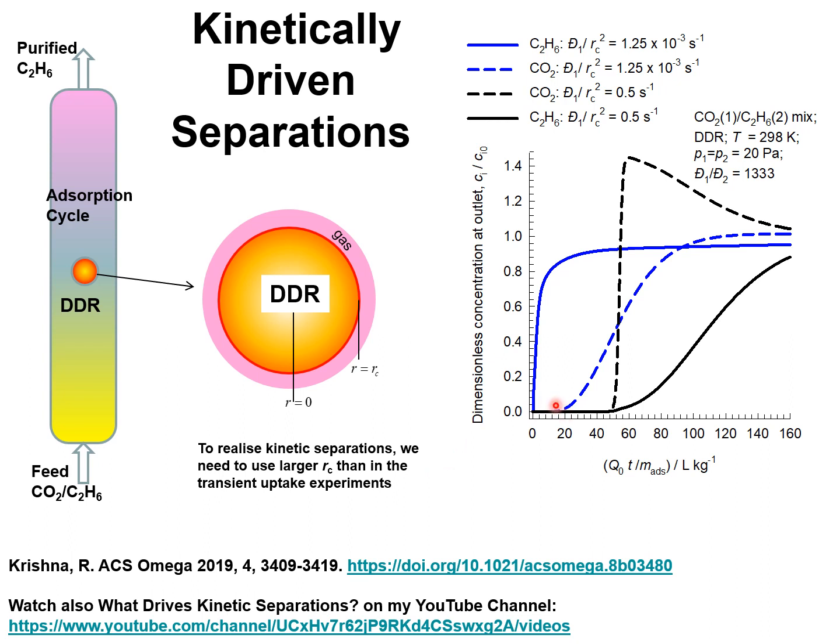The two scenarios are shown here. The blue lines are the scenarios in which the diffusional time constant D1/rc² is 1.25 times 10^-3. The continuous blue line is for the breakthrough of C2H6, and the dashed blue line is for the breakthrough of CO2.